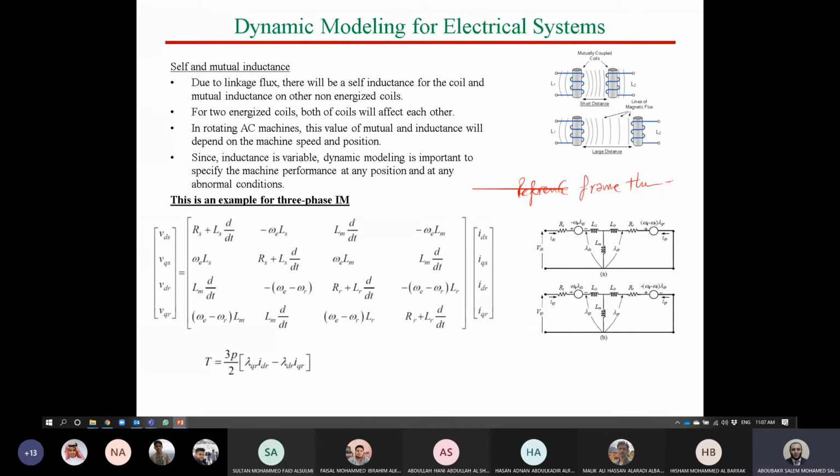And you will see the stator parameters, which were constant, now moving with speed ns. So this is called now reference frame. According to the frame that I stand on, I can see all of the other parameters moving at different speeds.